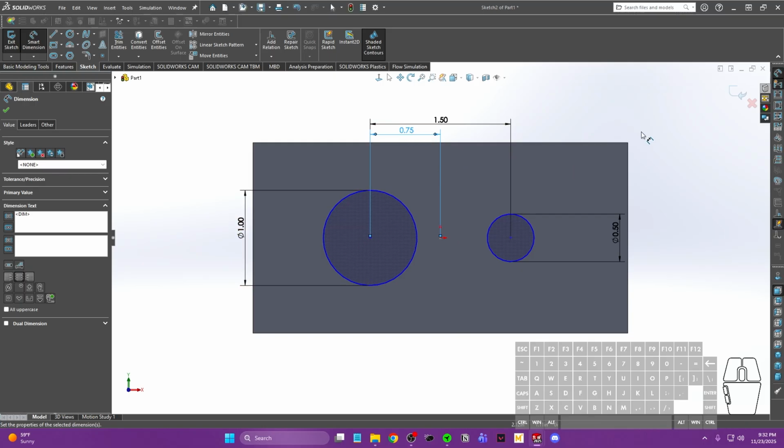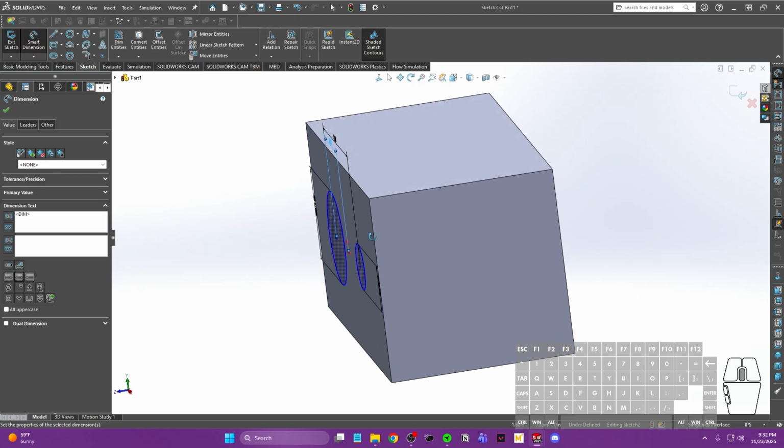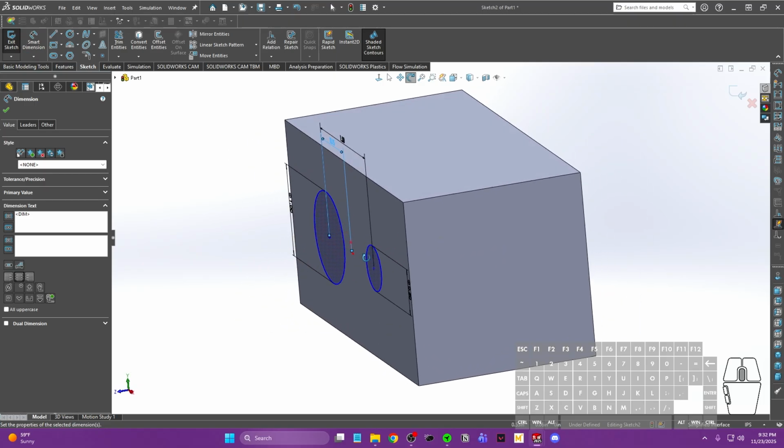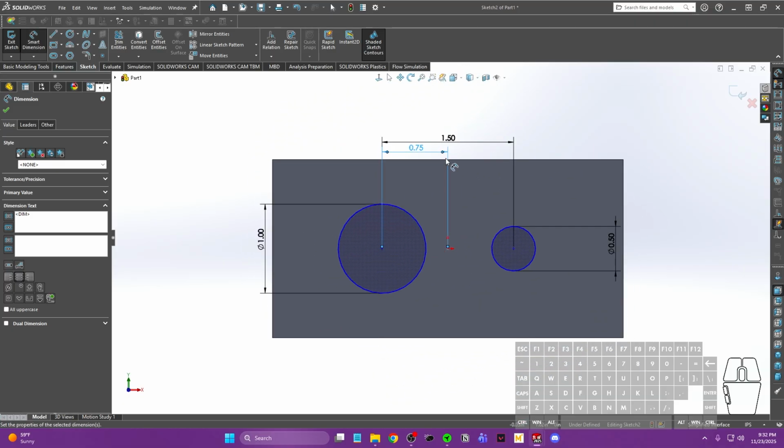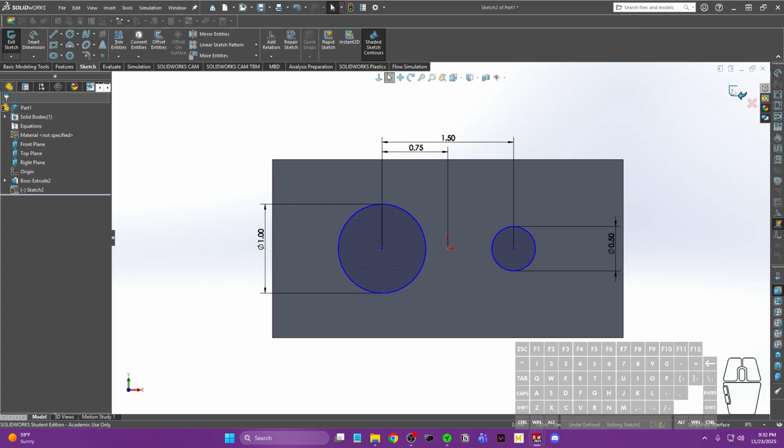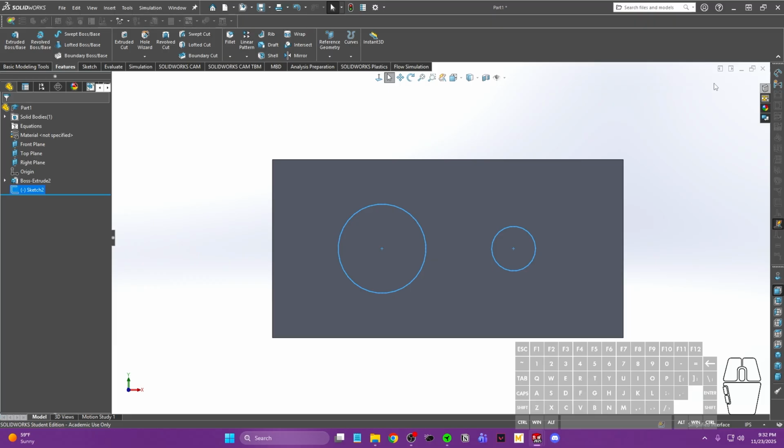Okay. So now we have 2 contours on this sketch that is on this face. As you can see, that's where the sketches are being drawn, on the face, not in the middle. Go ahead and press check. Check mark again on the right side to exit the sketch. And now with the sketch highlighted, I'm going to go ahead and do extruded cut.